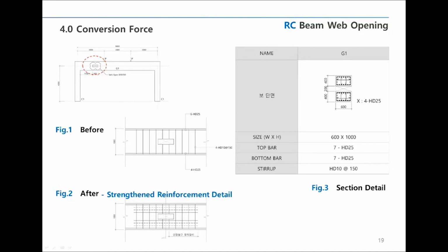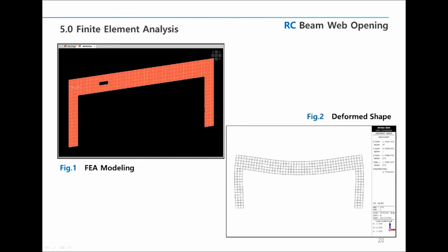I'll now move on to finite element analysis. Here I've used MIDAS Gen to review the contents described above as finite element analysis. So far, we have reviewed simple calculations with equal size of sections. But if the sections are not standardized, or if the size is different, simple calculation may be difficult due to the difference in stiffness. That is why finite element analysis is attached.